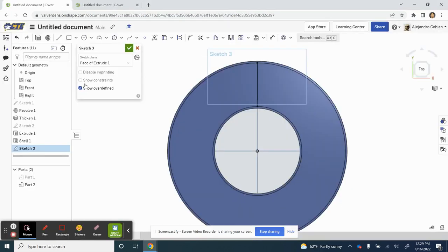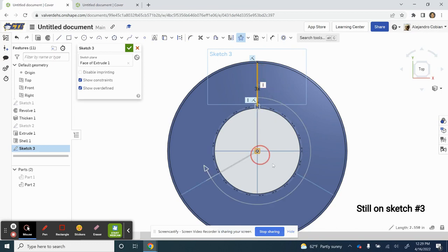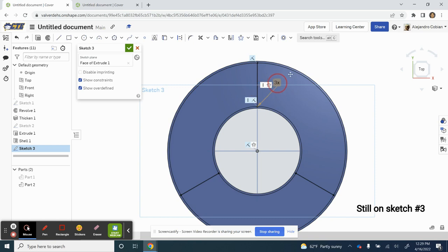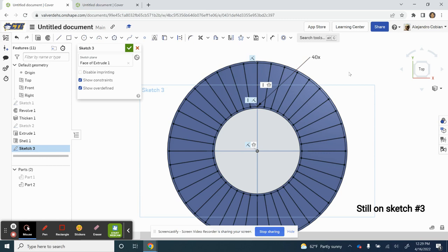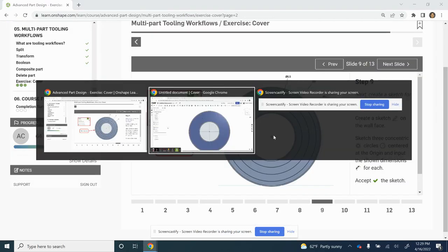All right, so let's just check our constraints. Coincident, and vertical, and vertical. All right, we're good. Let's click circular pattern. We'll click our line, and we're selecting it. So notice this, we can actually fix it on our origin. This is what we want. So let's click again, and we accept it. Let's drag this out, double click, and type 40. So by doing this, we do a symmetrical circular pattern all the way around our device with 40 lines. And we accept.